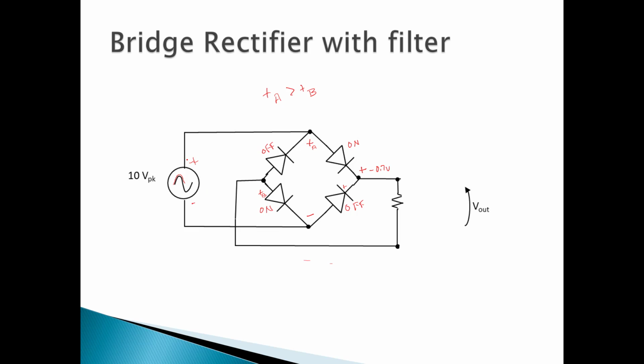So during the first half cycle, here comes the current. Where's the loop? Here's the current coming down here. Now we go through this diode. Now we go around through the resistor and back through that diode and into the bottom. So we got a complete loop. Okay? Now just for fun, let's see what happens if I turn this off. If I flip to the bottom half now, and maybe I can change the pen color. Wouldn't that be interesting?